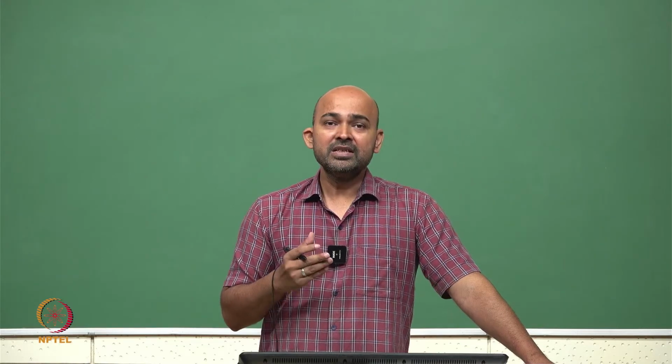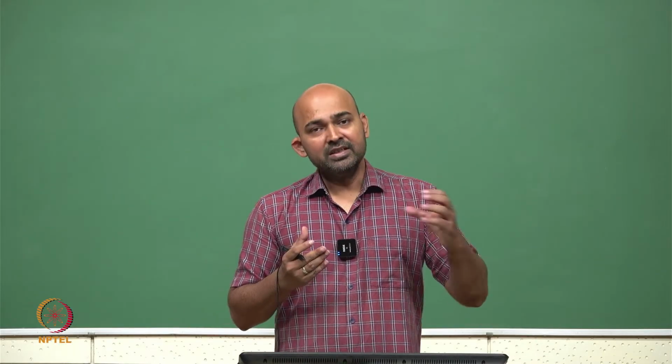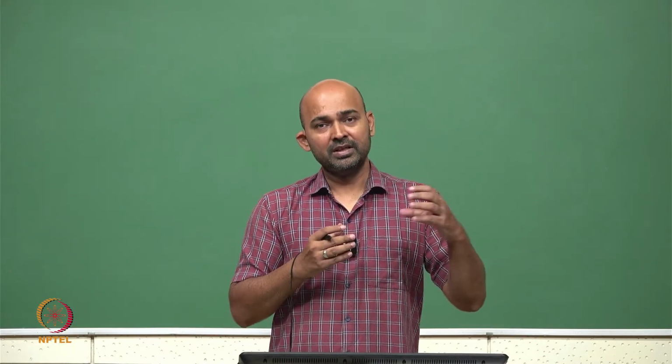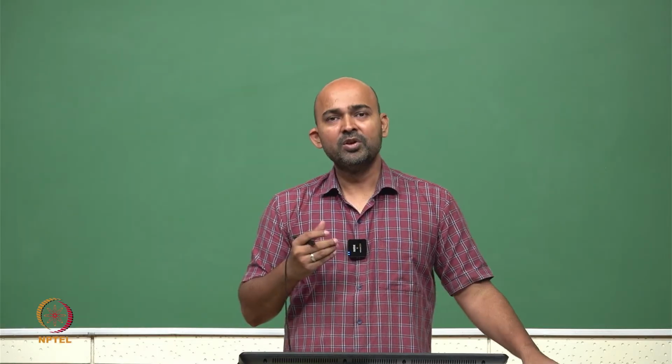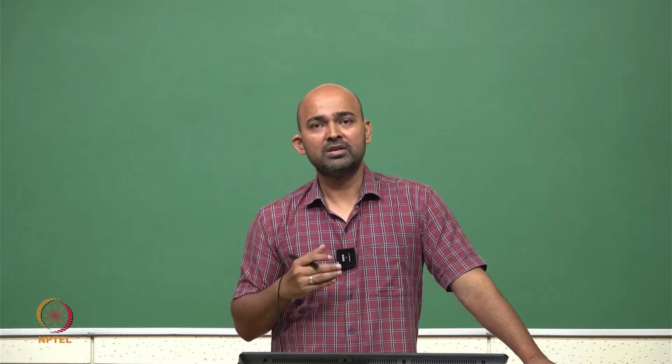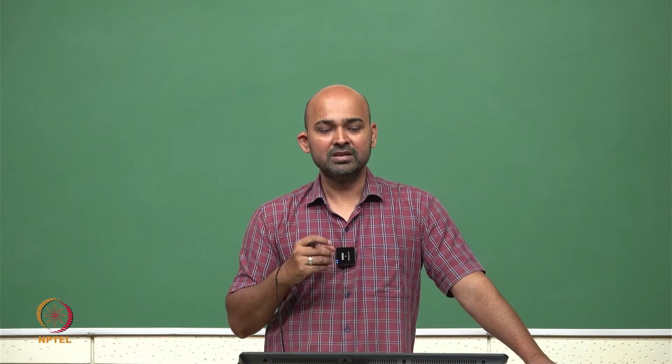The impedance matching is another important point in RF PCB. When we send these signals from the near end, let us assume that the characteristic impedance of the trace is 50 ohm, which is the standard 50 ohm termination throughout the world. We generally follow the 50 ohm terminations.